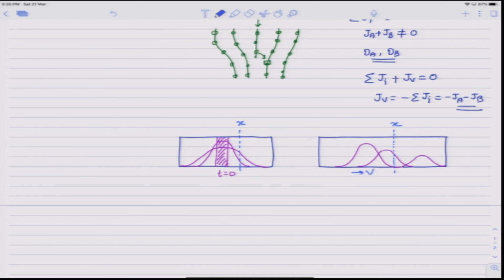How can we go about it? One easy way is I put some wooden chips on the surface of water and I track the velocity of the wooden chips, and I can approximately take the velocity of wooden chips as the velocity of water. Now, what is the criteria for a wooden chip to act as a marker here?